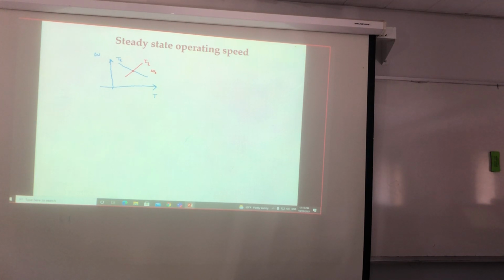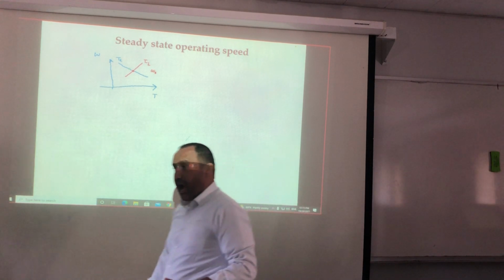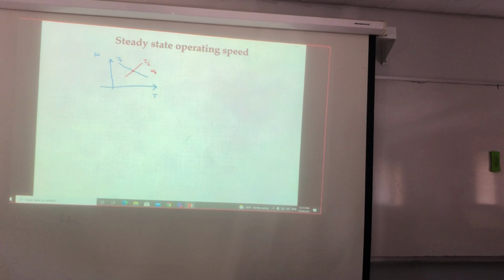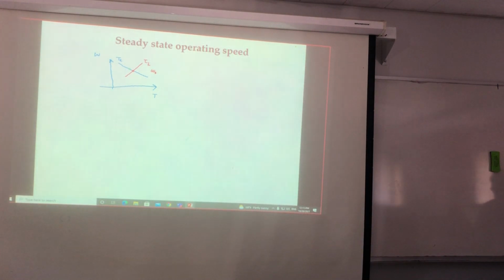So I am somewhere here. Now, the motor torque, is it higher than the load or less than the load? Less than. So if the torque of the machine is less than the load, can I accelerate? No. So this means that the speed will decrease until reaching the point. So I'm returning back to the stable point. Do you see it? This one here.